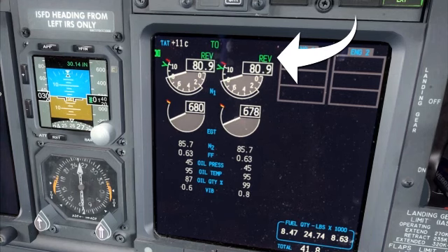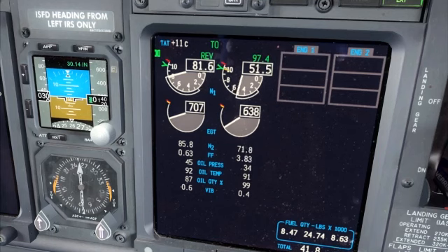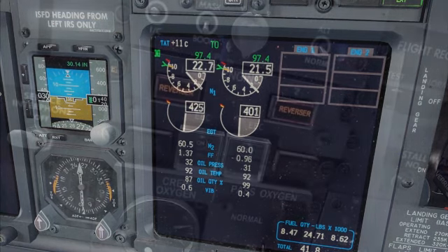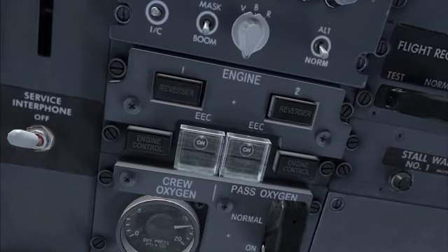In this condition, normal operating reverse thrust is provided and is sufficiently powerful to bring the aircraft to a stop. When added reverse thrust is needed for short, hot, or wet runways, the reverse thrust lever may be moved fully aft to the maximum reverse position. There is also a reverser light in the aft overhead panel that illuminates when the reverser has been commanded to stow. This light extinguishes roughly 10 seconds after stowage.